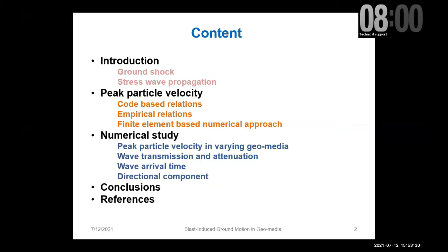The stress generated because of this ground shock, the parameters which are very important to predict this ground vibration, that would be in terms of peak particle velocity, and various approaches which are here with us to predict this peak particle velocity, which would be code-based relations, some empirical relations, and the finite element-based numerical approaches. Then our present study, which we have done, and the conclusions.